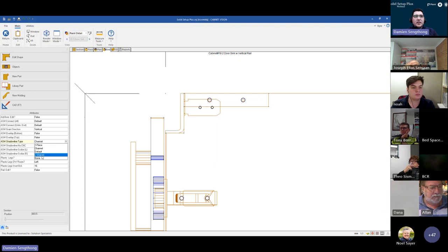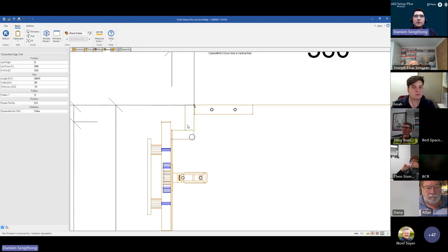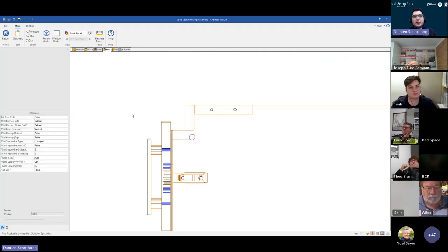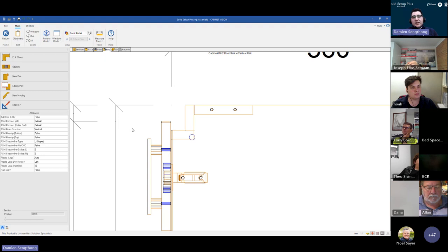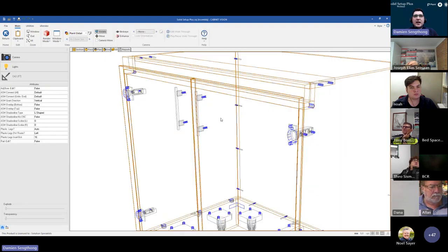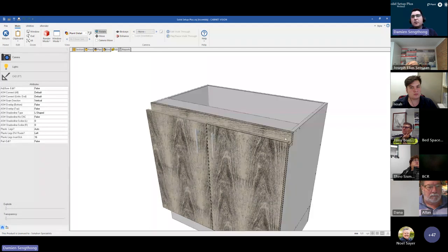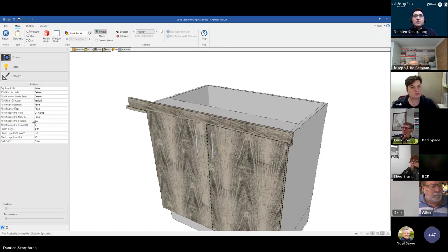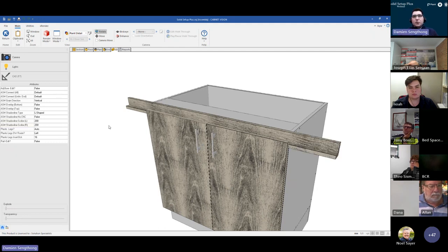And lastly would be the L-shaped configuration. Our L-shaped configuration will use our main front rail along with the return rail, and again, will provide you with the clearance hole. Along with activating the shutter line, we'll give you further attributes to adjust the scribe of the rail, either left or right. As we can see on our left-hand side, we do have attributes for scribe left, and then attributes for scribe on the right-hand side. If you were to use a scribe, you would probably just configure the sizing based on one cabinet.